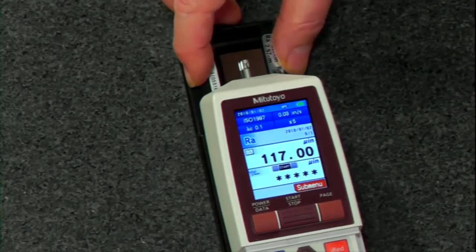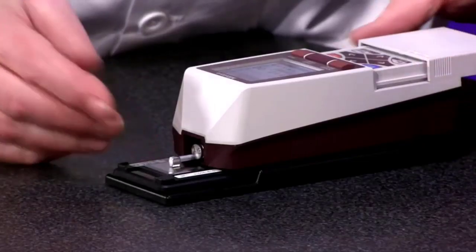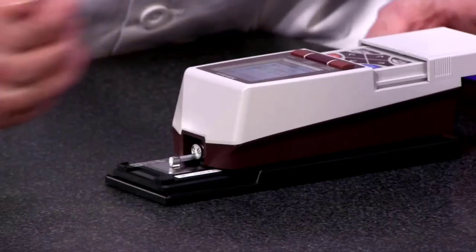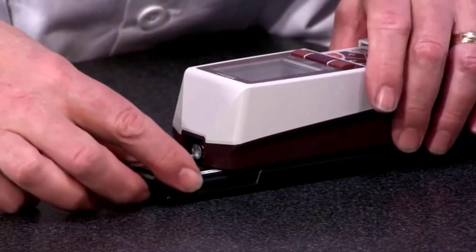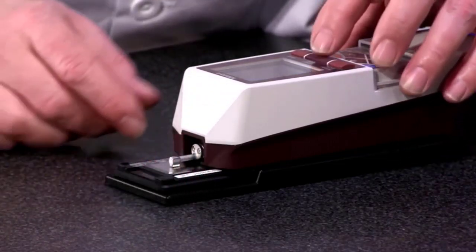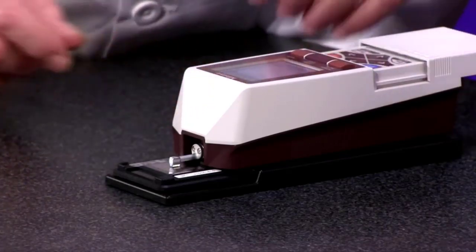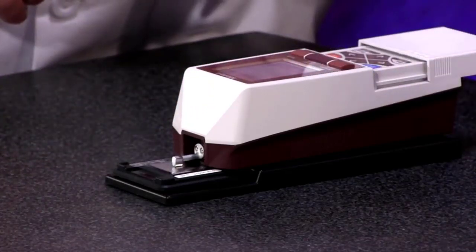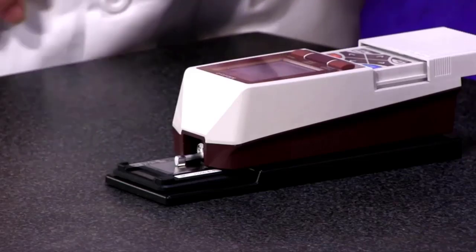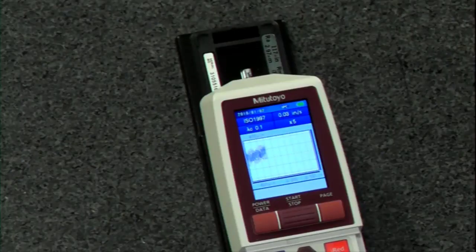So we're set up on the stand. It's critical that you have the lay of the lines perpendicular to the stylus. That's very critical. You can't just slap it down and hope for the best. You have to pay attention. Push the start button, and we won't want to touch the table or move anything. It's taken its measurements. It'll take a series of 5 different measurements, to what we have it set to, and then it will average them, and we'll see how it goes. You'll notice the screen will self-correct when it gets near the edge of the screen one way or the other, which is really nice.